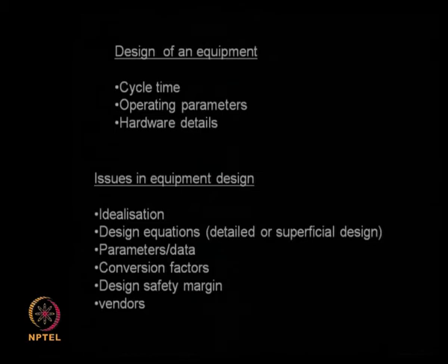So if you are very serious about the data, you may have to go to the lab and try to collect data. If you want to know the viscosity of a liquid, you go to the lab and get the viscosity data for the liquid. If I want to know the surface tension, either I assume some value from the net or I actually calculate surface tension. If you want to know viscosity effect as a function of time and temperature, we may have to do the experiments, or you may assume an approximate, like linear change between temperature and viscosity.